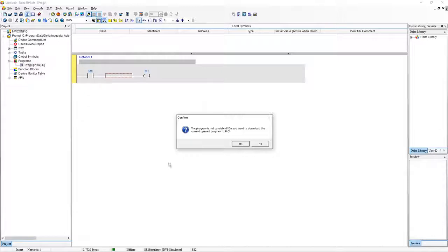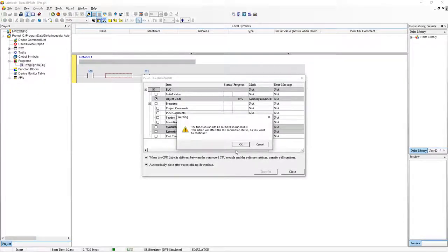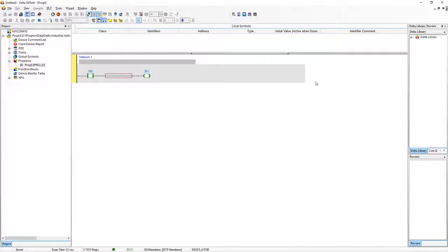From there it's going to ask you if we can download to the simulator PLC. So say yes. Now there's going to be a transfer process. All of this will be the same in a real hardware PLC. Then just something to note, just to make sure, is that this little box over here says run. If it does not in your case, then go up to this button here and you can click on run or stop to stop the PLC or put it into stop mode, as we previously saw in other lectures with, for example, that hardware switch. Here we can do it via the software.